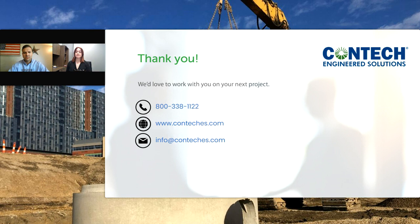Thank you, Taylor. Are most of these units traffic rated? Yes. Sorry, Marko, I feel like I'm just taking over. No, take it, fire away. Our standard loading is HS20 or HS25. We can do custom loading if your site specifies it. We've done airport loading. We've even done a dock for boat loading before. So if that's something that you need on top of just having that HS20 or HS25 loading, we can get that custom made for you. But again, standard is highway loading, and we're good.